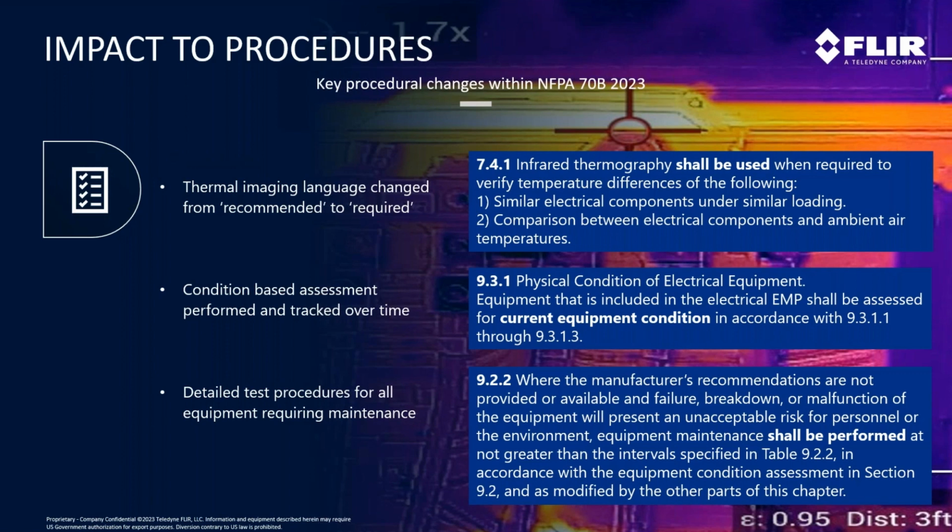The important component here as well is that these particular activities, at a minimum, for any electrical equipment that is documented within NFPA, and it's all spelled out very specifically, the minimum thermography is to be done every 12 months, and that's typically based on condition. There's also condition coding within the guidance, but no less than every 12 months for your inspections of your electrical equipment.